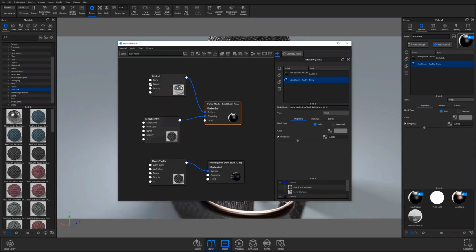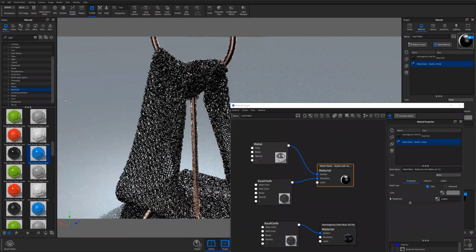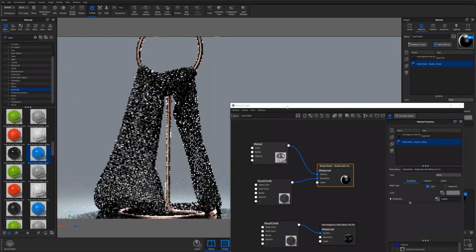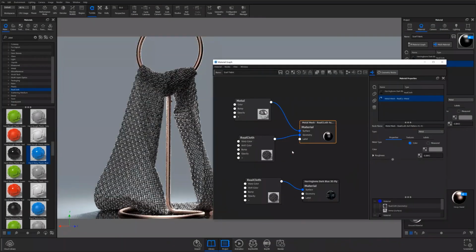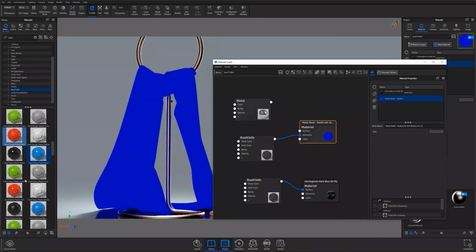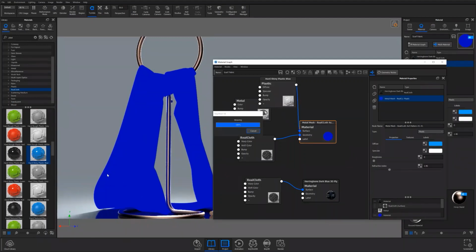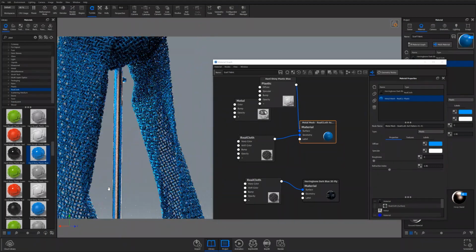And then I can grab whatever material I want and put it on there, and then that surface is going to reflect that material. So maybe let me get a red plastic or something to show you how that works. Let's use that blue plastic since KeyShot's blue. Let me move that to the side so you can see what's going on here. So I'm going to pull that off of the surface node, and immediately it goes blue. It's losing that surface information. But if I pull in that blue plastic and then I attach it to my surface, it's going to weave, it's going to set up again, and now you have a plastic mesh that has the characteristics of the material.